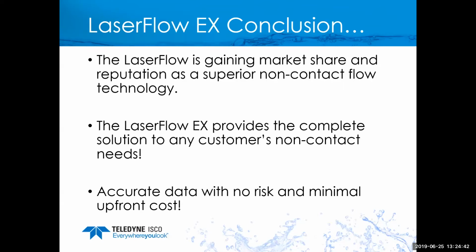We also see people now trying to verify their flumes are right. What I've seen, and I've been doing this for quite a number of years, is that just because you have a flume and you have your ISCO handbook, you can see that it read the level right and it did the math correct on the meter, doesn't necessarily mean that flume is right. So a lot more verification of flumes and primary devices up there.